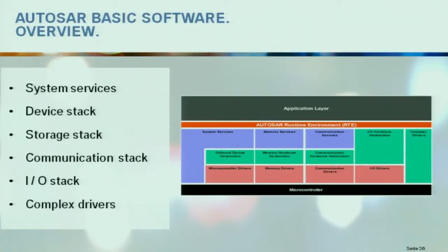And the storage stack abstracts between different types of memory. You can have flash memory, you can have EEPROM and things like that. And you can even have external flash or internal flash. And the memory stack provides a uniform interface to all those stacks so that the application does not have to take care about to which storage stack the data go. It has to be configured only in the runtime environment.